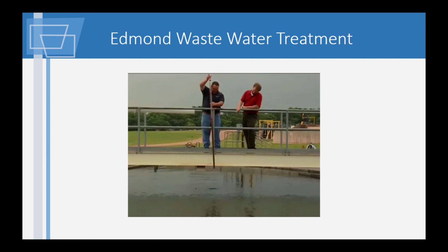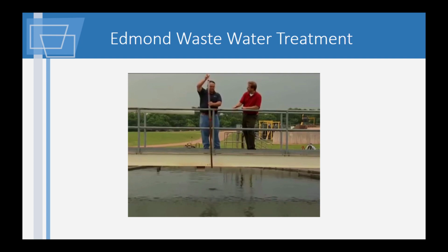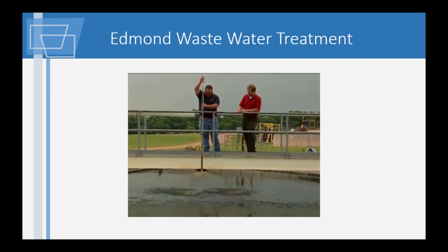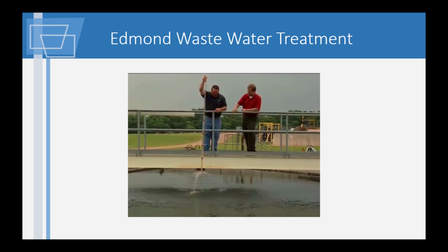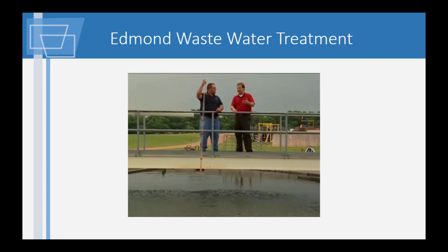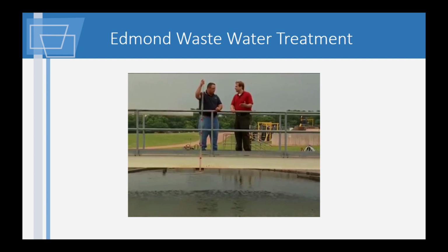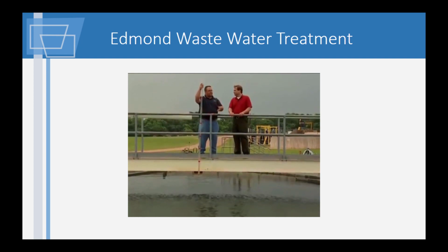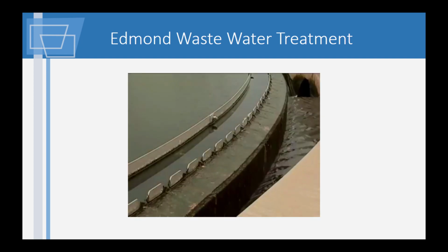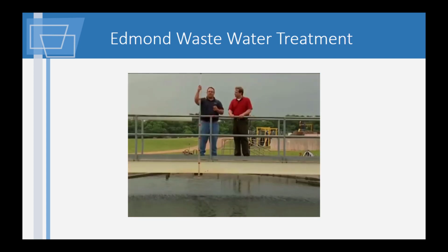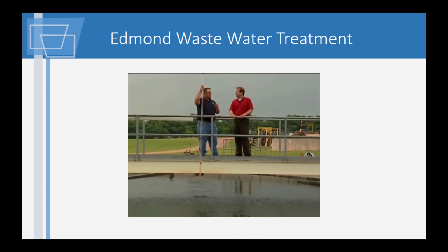Wow. Okay, so you've got almost 4 feet, 3.5, 4 feet of sludge. And then that's the clear water that comes out of it. Okay, now after this, then we've got another step because it gets even cleaner. So we have little fine solids that'll actually make it over the weirs of the clarifier. And so our next step is to take it to a sand filter and get it down to just a teeny tiny little bit. Okay, where's the sand filter? Well, let's head there.